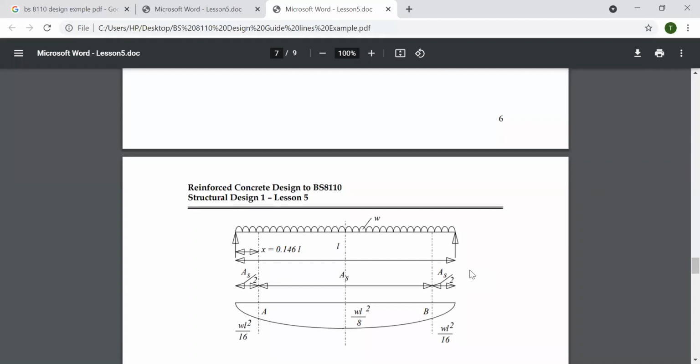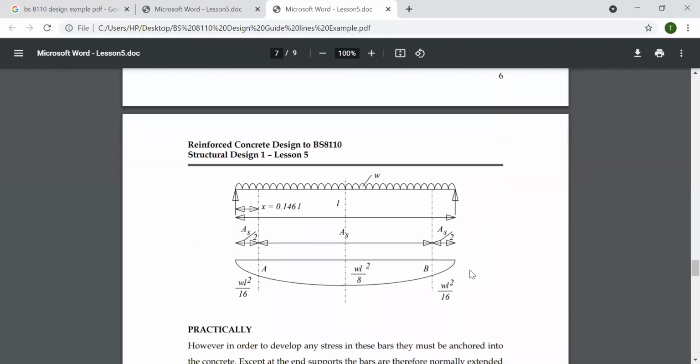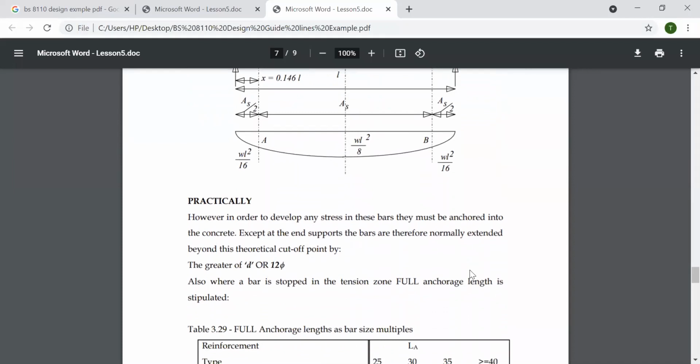if point loads come. So the curtailment would not be possible in a different section, because sometimes the higher moments come closest to the support. Then once you are going to do it, it won't be easy for the site to manage. So if you are doing the curtailment, you should practically see two different things. One is if it is possible at the site. The other one is if it is really making savings or is economical. If these two are working, then you can still go ahead.